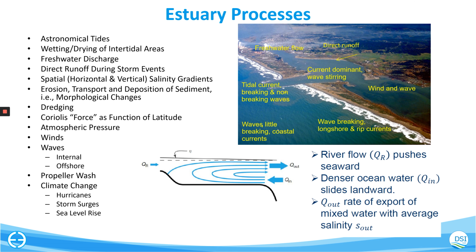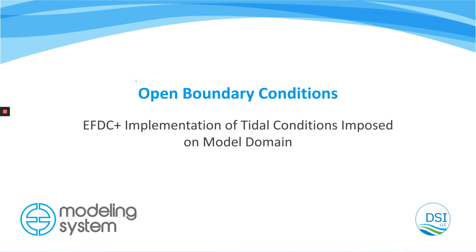So as that says, open boundary conditions. I've seen a lot of models that have very poorly configured open boundary conditions. That's actually one of the most common problems that I see when users post their models on the forum, or when they send their models to support: poorly configured boundary conditions for an open boundary. This can cause all kinds of funny things to happen in your model.